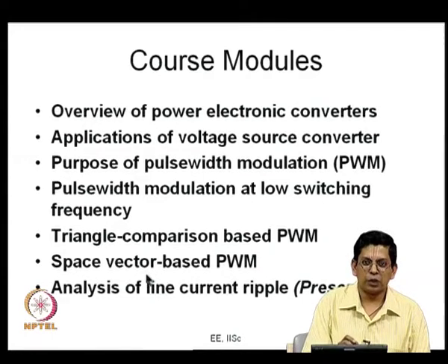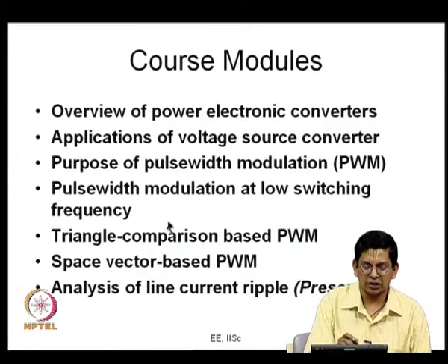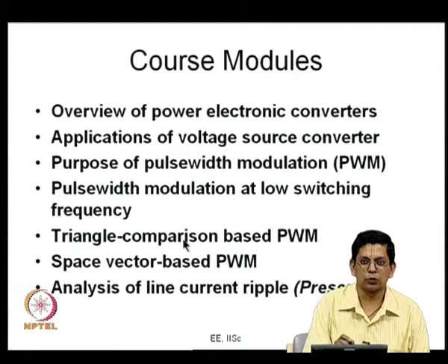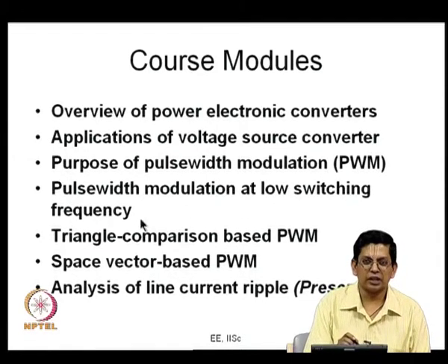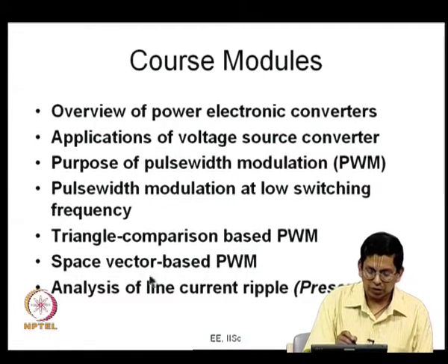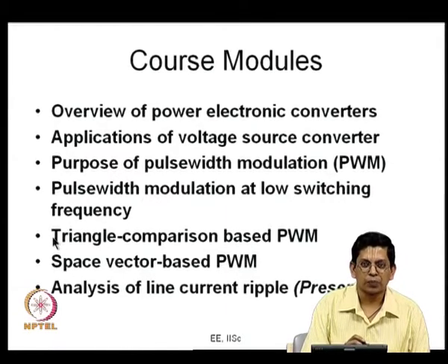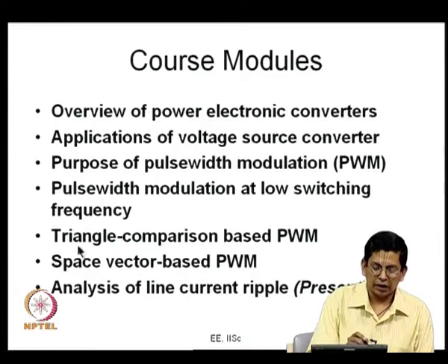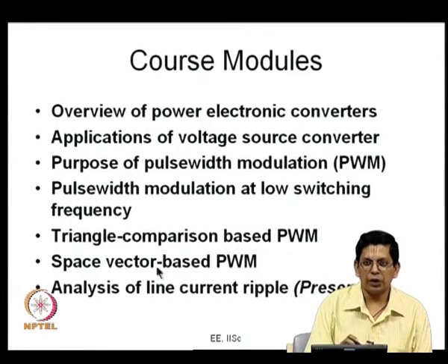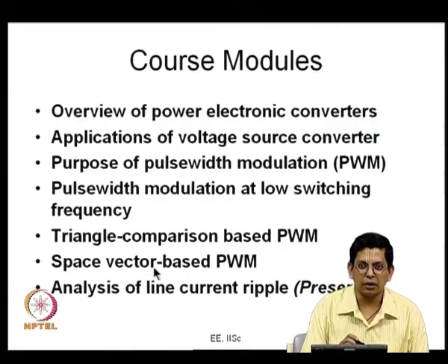So, we considered very low switching frequencies such as one switching angle or two switching angles in every quarter, and then we tried to see how with just two switching angles we can control the harmonics and so forth. And from that we went on to selective harmonic elimination and offline optimized PWM. And subsequently we moved towards real time generation of PWM, which is what is most commonly done. And again it is not at low frequency, but at frequencies much higher than the fundamental frequency.